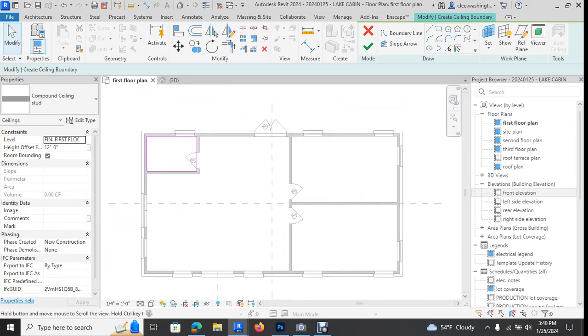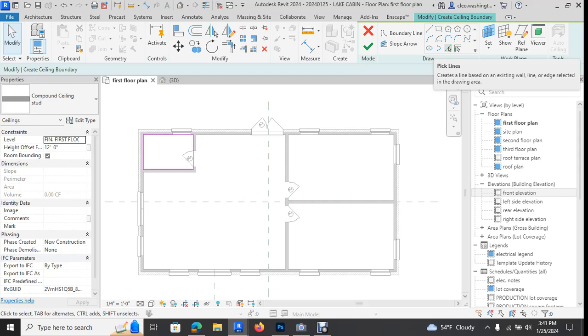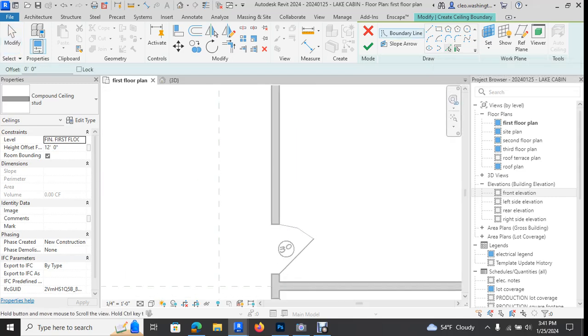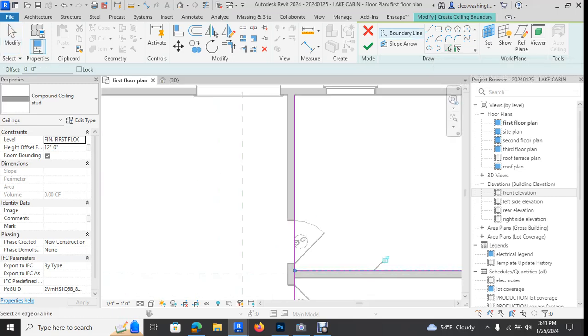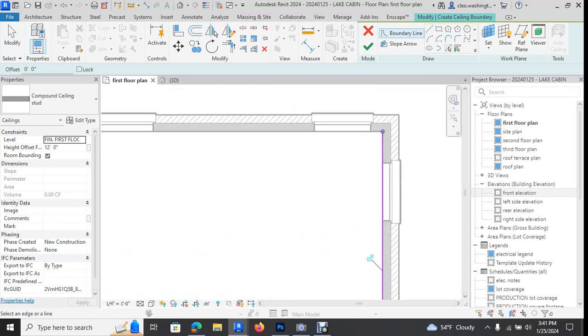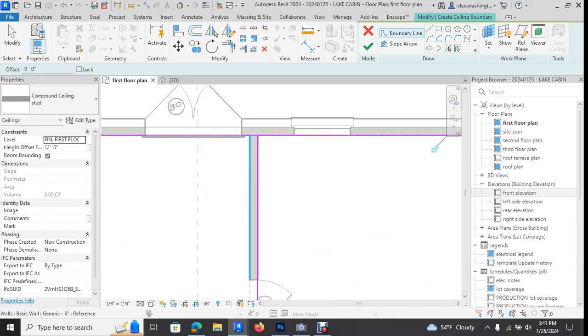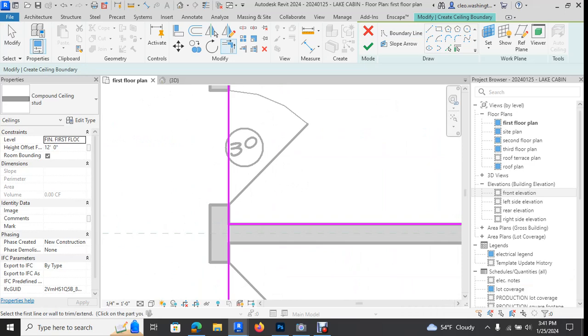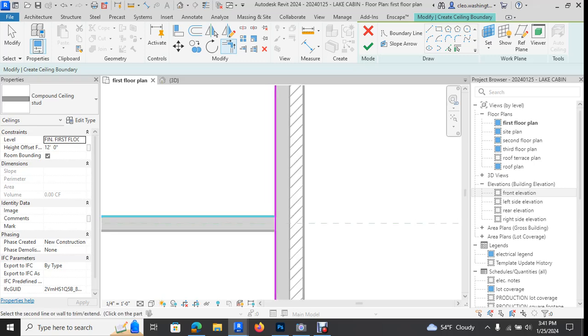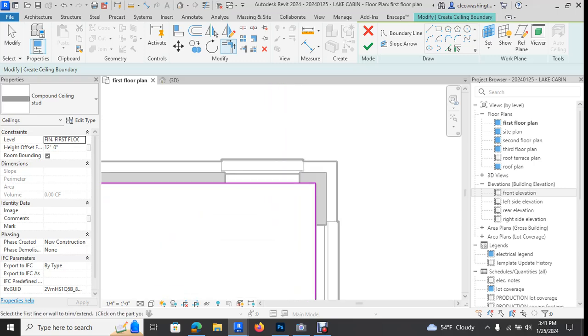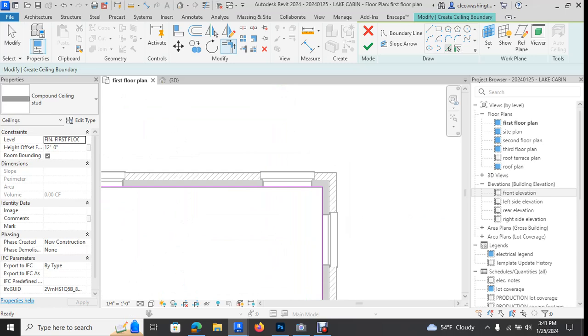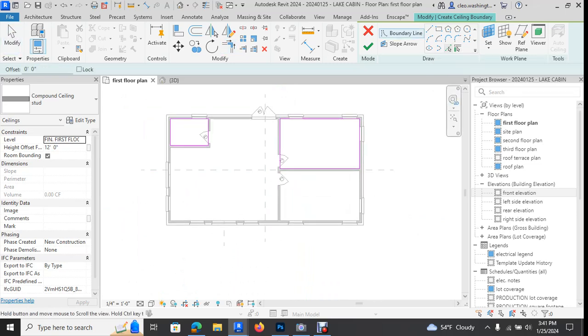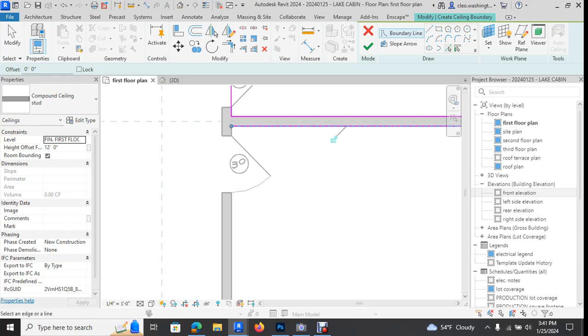And also, let's go ahead and put the ceilings in for the bedrooms. So you go here, here. You have to do them one at a time. Here. Okay, then TR. Okay. Now click the pick lines command again, and let's pick the ceiling in this bedroom.